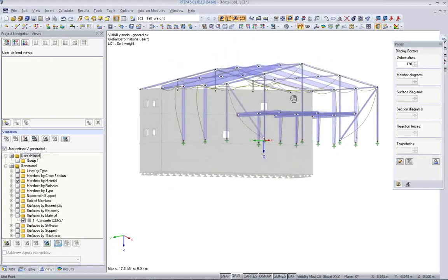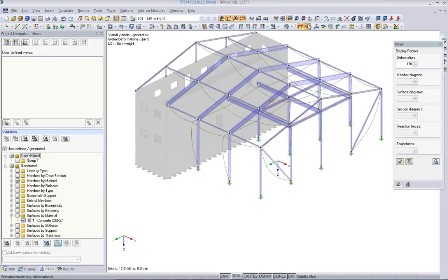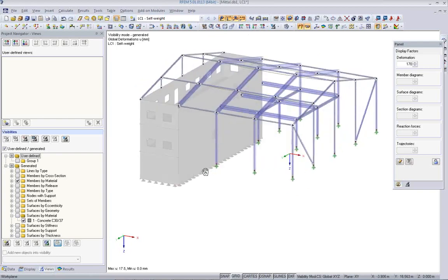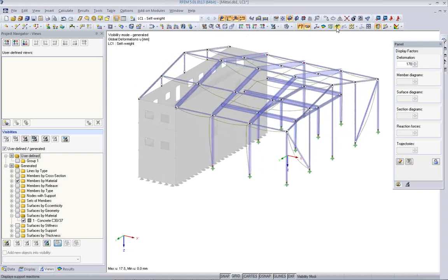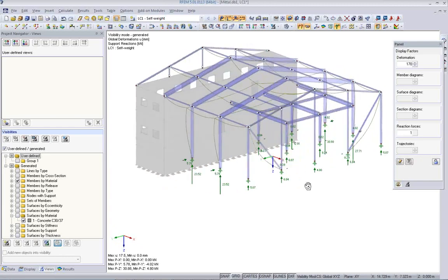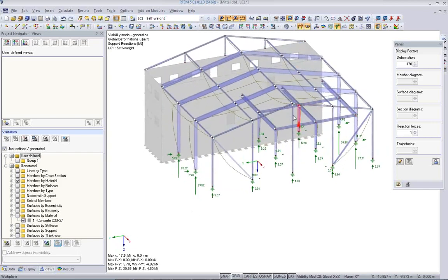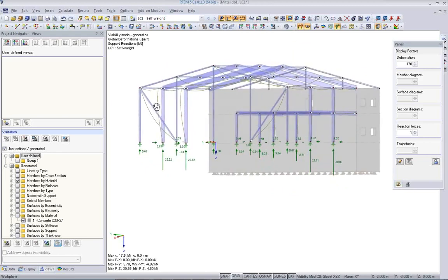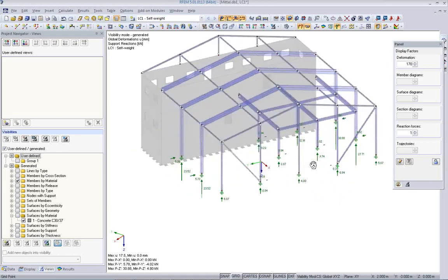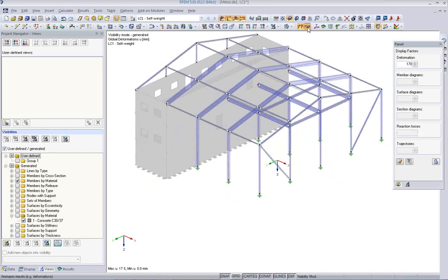So we can see here the deformation lines of the members. I can animate them, and this way I can usually find if there are some loose parts, and it looks all good. Also, the support condition should be more or less symmetric, which is here at the corner columns, and there's a little bit of difference because here we have this floor structure, but it looks quite okay. So my model is of good quality, and I can continue doing the design process.